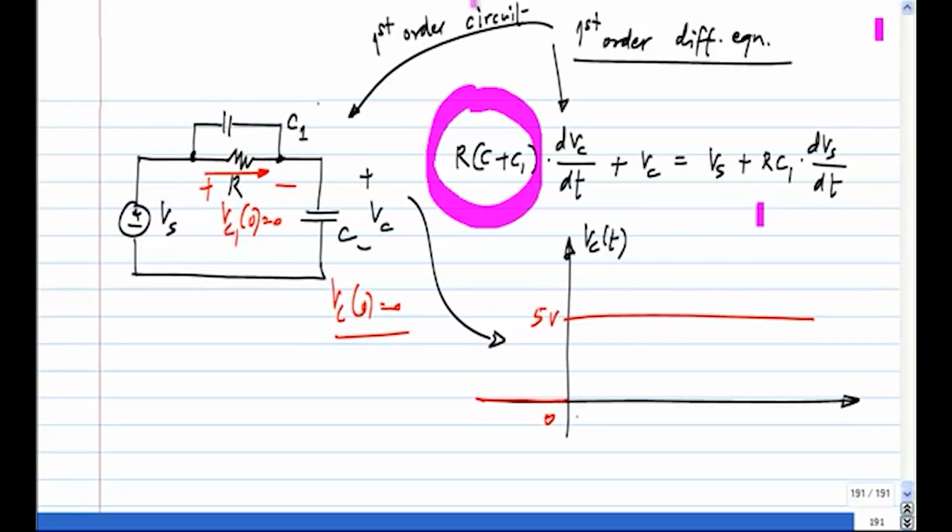We already concluded that both the voltage across C1 and C will jump, so the currents through C1 and C are both infinite at that instant. Not before, not after, but just at that instant. But the current through R will be finite. As far as KCL here is concerned, we have some finite contribution and two infinite ones, so we can completely neglect the resistor.